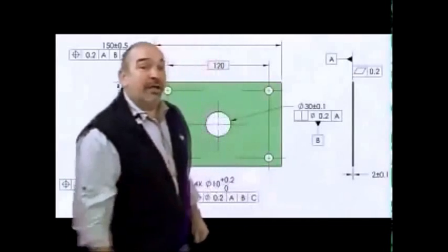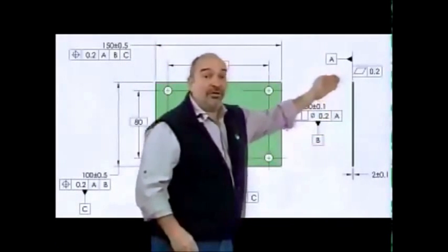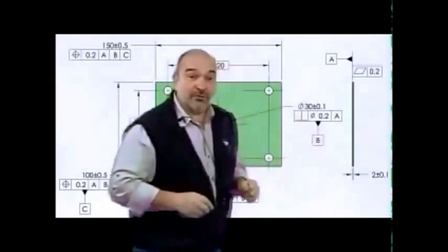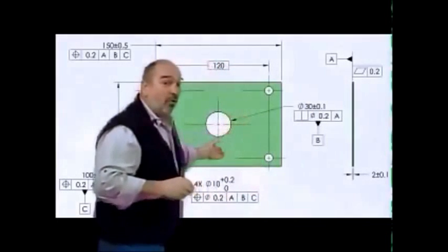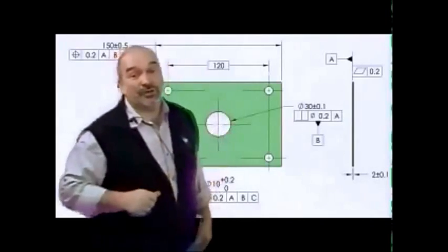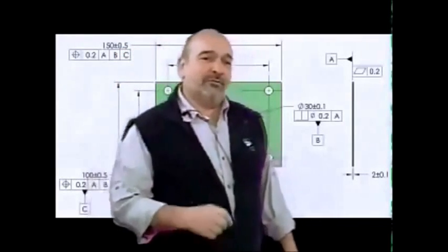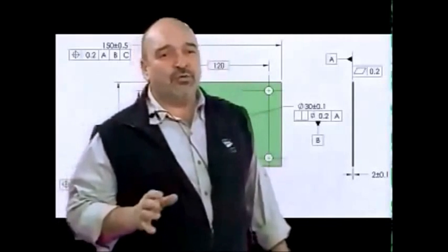Now the second drawing has a large flat surface as a primary datum feature. It can arrest 3 degrees of freedom. The center hole then is your secondary datum feature, and now it only has to take away 2 degrees of freedom, which it can reproducibly do. The datum features you pick have to be usable.